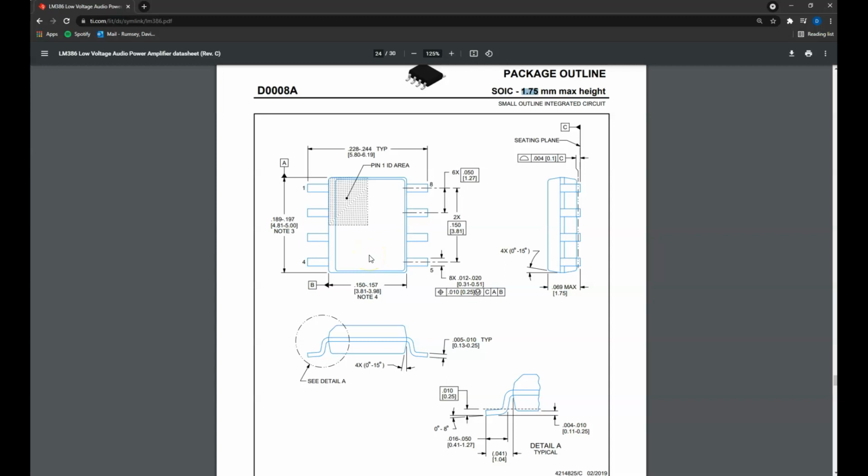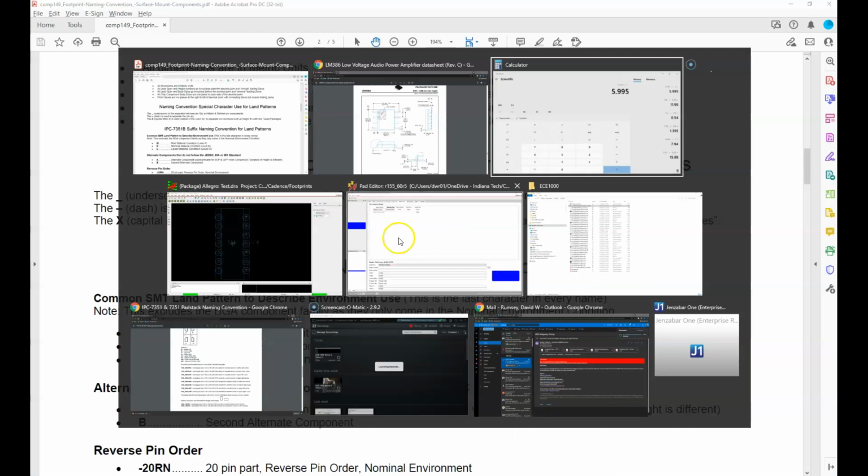You might say, well, we did it differently for the other one. Well, that's because we had pad stacks that actually had drill holes with copper pads surrounding them, and we could have a different size for those copper pads based off of whether we did level A, B, or C. So we have to be able to indicate that in the footprint name when you have those through holes. But since this isn't a through hole, there's not really an A, B, C level because it's the chip. There's nothing we can do as far as making these landing pads bigger or smaller. So we don't need to put any kind of suffix on there.